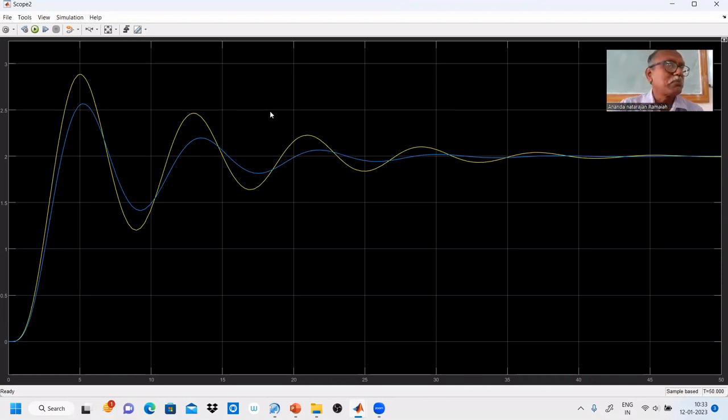You can understand how important tuning is. The continuous cycling method only gives perfect tuning rules, tuning values. That's why it quickly settles. Even at 35 seconds, the reaction curve method is not yet settled. But here you see that at 30 seconds, even 25 seconds, the continuous cycling method settled.